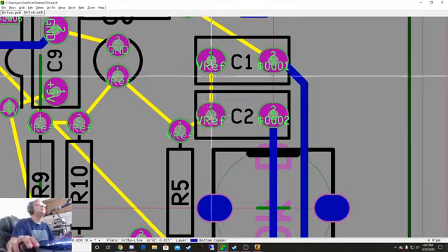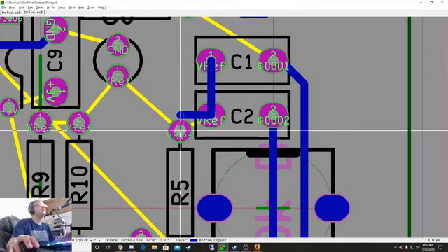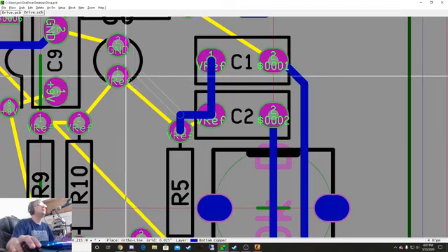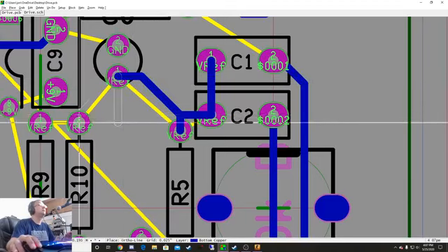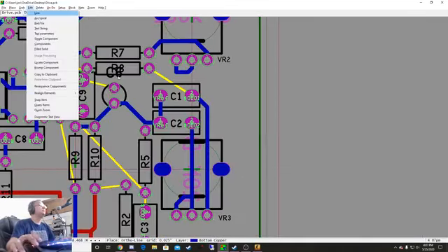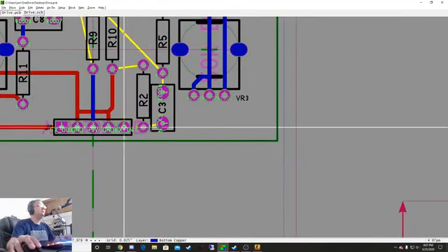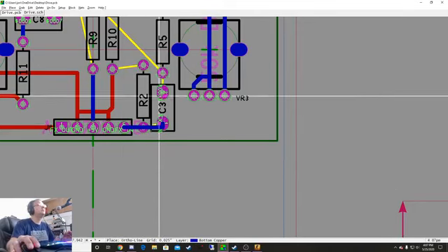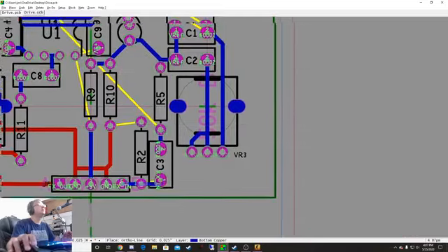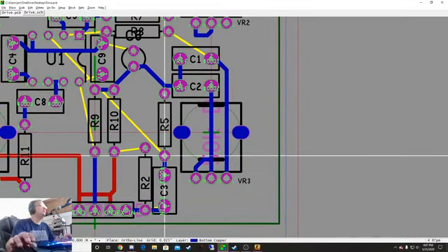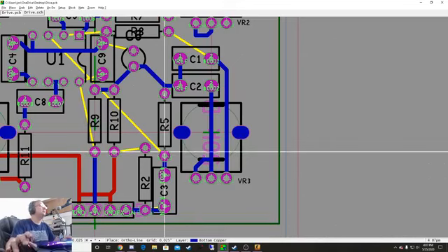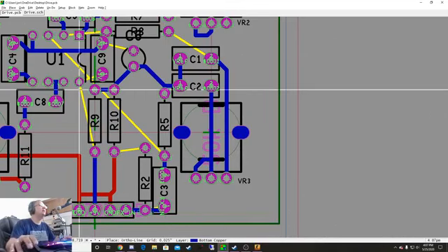So we're going to route VREF. All right, FX in looks like it's pretty safe to route. This is a sensitive trace, so I want to try to get that there as simply as possible without getting in the way of anything.